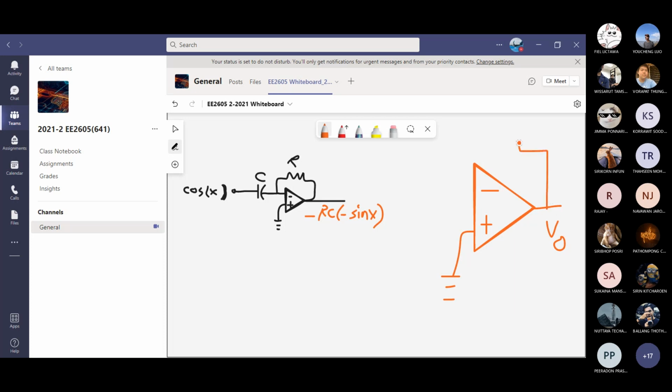For the summing op-amp, you have a feedback resistor. And then you have an input resistor. It's up to you. Can we make a unity gain summing op-amp? Means everything is the same ratio. If I take here, let's say 2.2 kilo ohm, 2.2 k ohm, and this one is 2.2 k. So this is called a unity gain. The gain is 1.